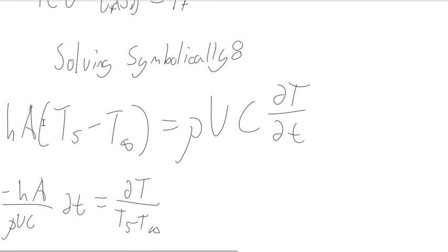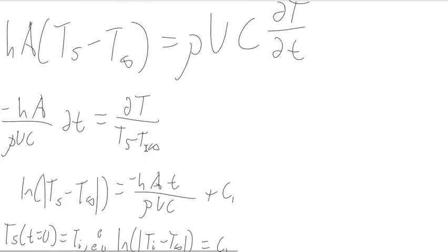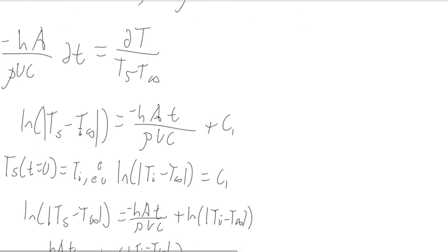And just plugging in the energy balance equation with lump capacitance, I'm assuming radiation is negligible here, so we just have the energy either going in or going out, depending on how you look at that, equaling energy stored thermally. And from this, I'm just trying to solve for C, right?